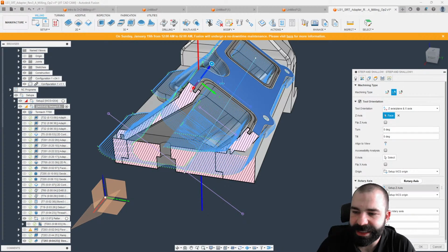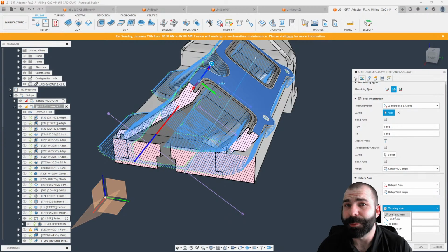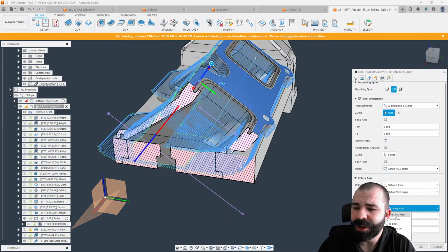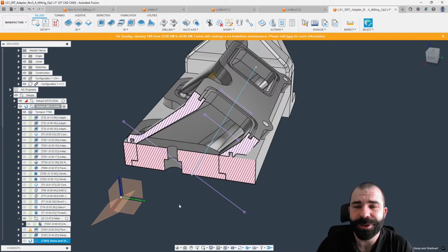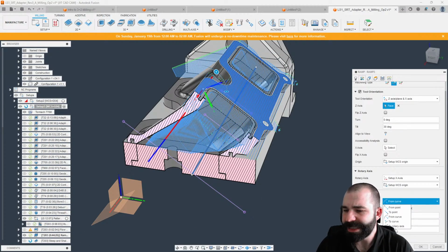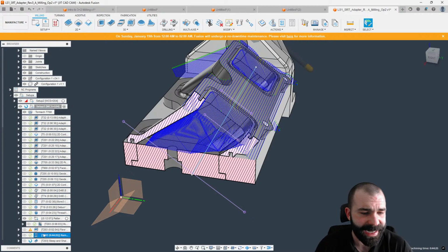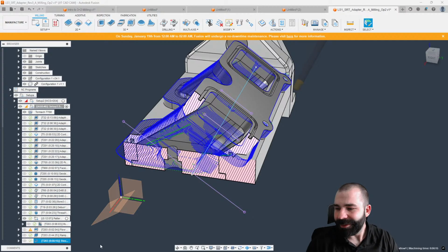And what you're going to see is, again, we have to redefine setup X. Of course, it's 2 rotary axis. We could also do a lead and lean here. If I remember correctly, I don't think we had lead and lean when we were talking about ramp, but we could always go back. What lead and lean allows you to do is to actually set that tool at an angle versus doing through contour. But we're going to let that calculate. Let's check ramp one more time while that calculates. We do not have lead and lean here inside of ramp. So that was one of the things that I did know that we were going to get inside of steep and shallow. So I am going to let this go.